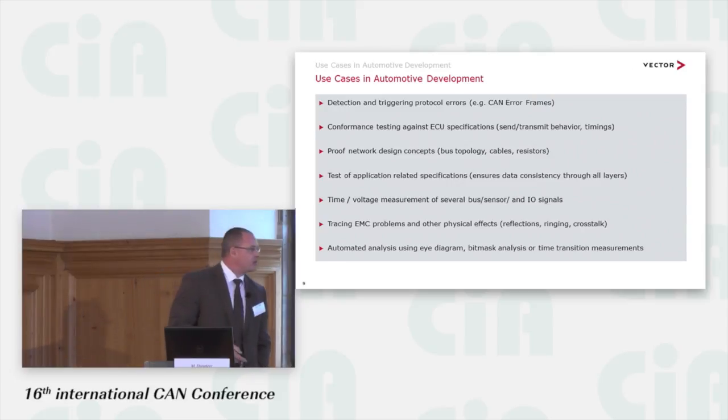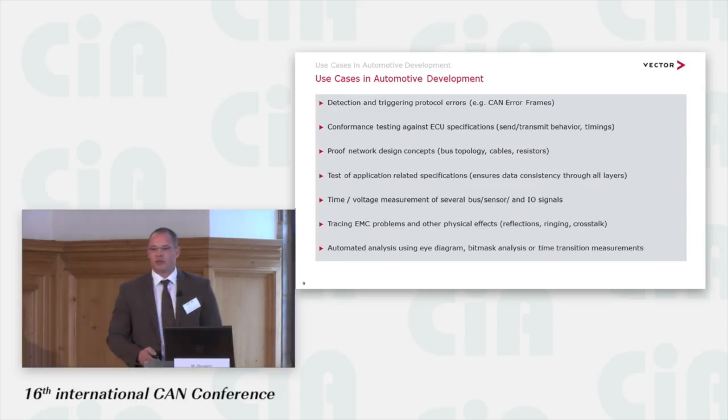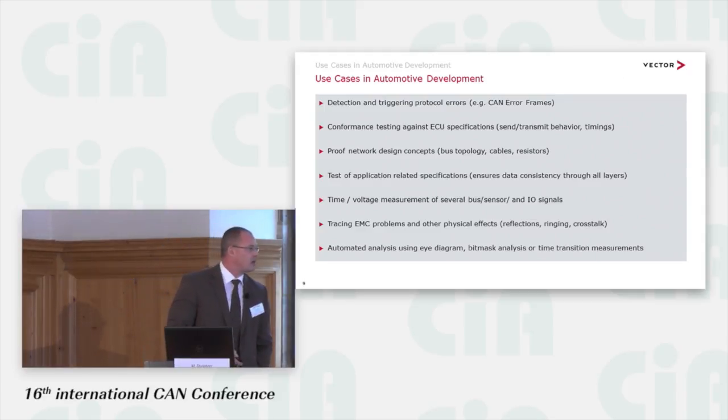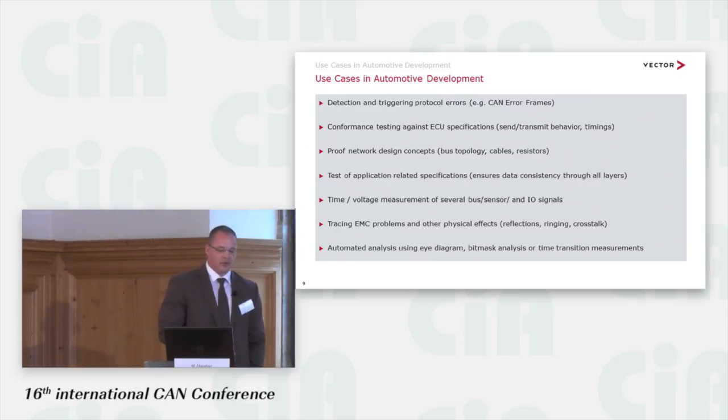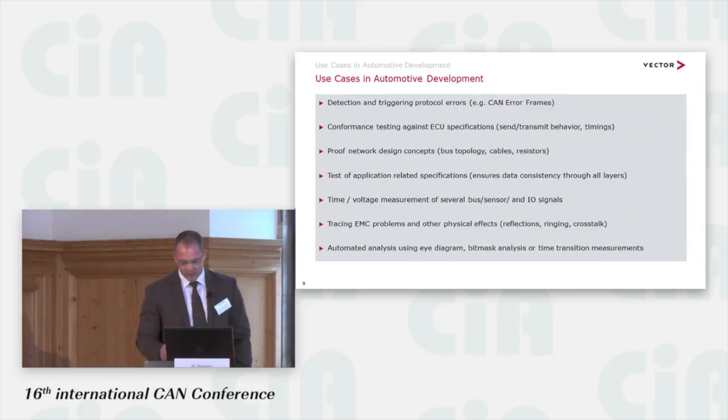Another important thing is that you have the possibility to establish your own test scenarios by using some methods like eye diagram or bit mask analysis. I will come up in detail later, or transition time measurement. You can measure the time of rising and falling edges.